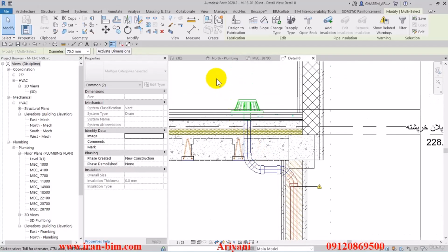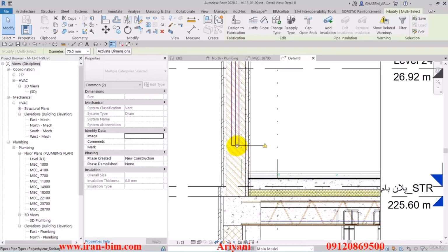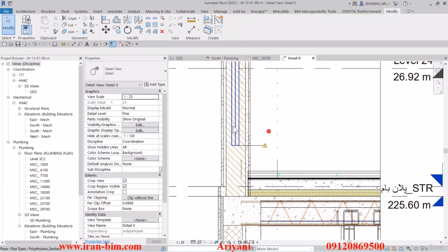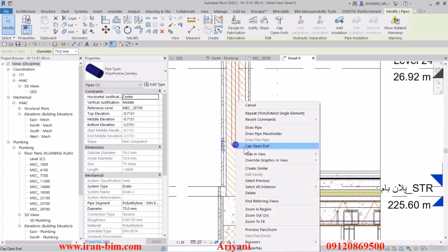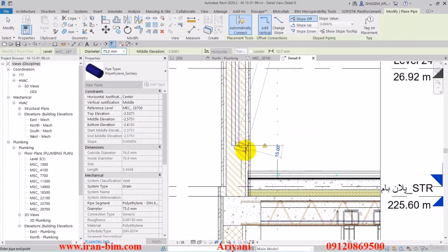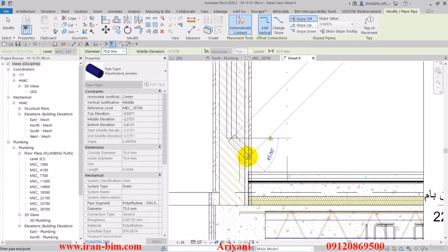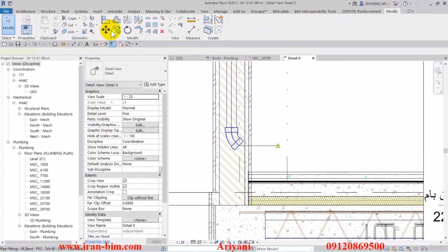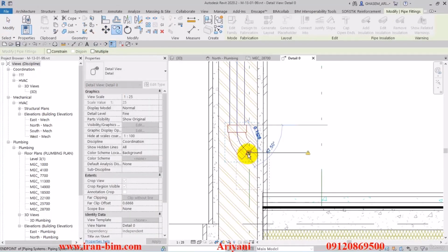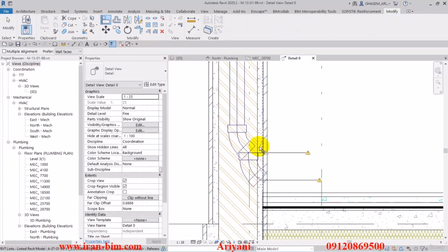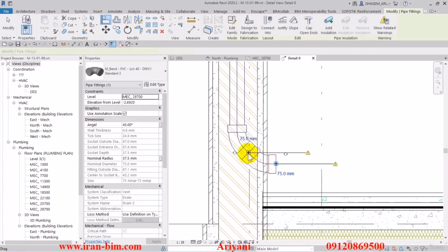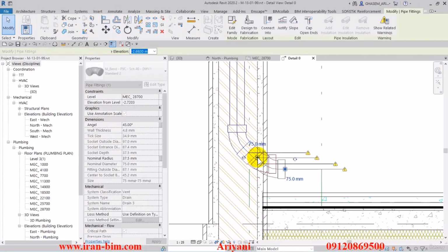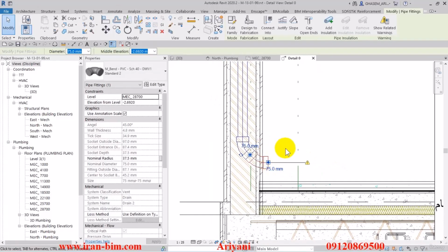Alright, and then after that I'll select the piping once again and then right click on it and select draw pipe, and using a 45-degree angle once again I'll draw a pipe, then delete the extra bit, then I'll get a copy of the rotating bit, paste it down here, and then using a line I'll lock it to our system. Let me just move it outwards a bit and then I'll find the connection point once again so that we can patch it up.